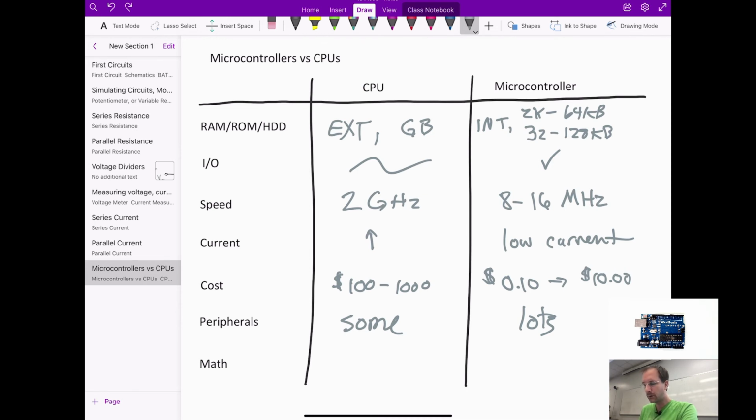usually CPUs are heavily optimized and have a lot of silicon devoted just to doing mathematics very, very fast. This is usually called the ALU, or arithmetic logic unit. A lot of CPUs these days don't just do single-cycle multiplication, but they do many multiplications in a single cycle. And so if you're running at 2 gigahertz, or 2 billion cycles per second, you can do around 2 billion multiplications per second, which is just fantastic.